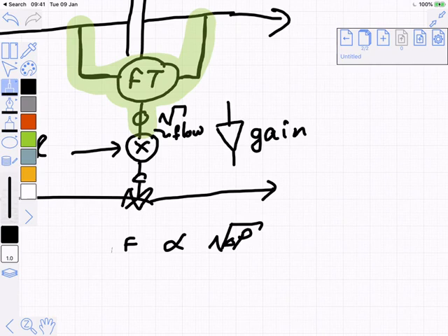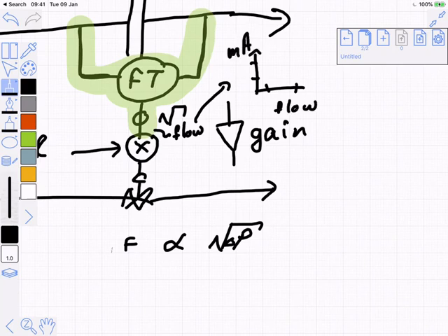There's no signal saying 2.4 cubic meters per second. There's a signal saying 12.3 milliamps. And so there's a conversion factor there, which includes encoding in that electronic signal over there a flow to milliamps. And that's probably the only way that I'm going to multiply by something.